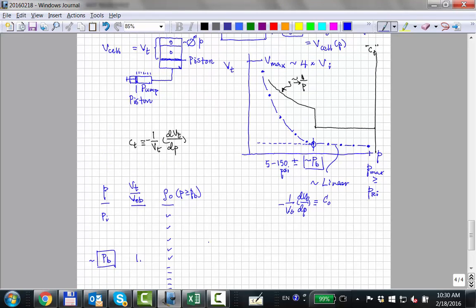When they inject the sample into the container, they either do it from separator samples and they actually know the mass of separator oil they put in and the mass of separator gas they put in, or if they inject a reservoir oil sample, then they would know the volume they put in, and they would have to have measured the density independently. Basically, you know the volume that you move into the cell at a fixed pressure and temperature, and you'd have to have the density at that pressure to get the mass.